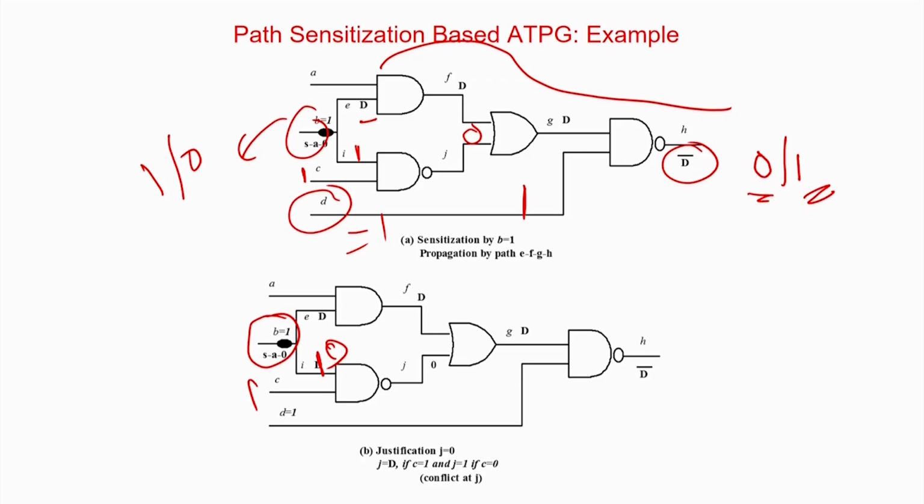Now it is a 3-level circuit; in this case it will be a very high level. This level means I am talking about these levels, this is a 1, 2, 3, 4 level circuit. It will be a much higher level circuit, and things will again blow up because the number of stuck faults will be higher. Sensitize, propagate, justification will be difficult because there will be so many alternative paths to try and so forth. So there the optimization will be at a higher level of test, not even at the gate level, even at the black box level, like adder.